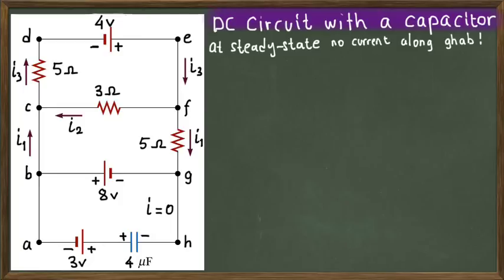Well, by setting this condition, we are ready to apply the Kirchhoff rules to our multi-loop circuit. So we start with, let's say, junction C, and of course when you put I equal to 0 for this branch, then there will be three different currents flowing in this multi-loop circuit, and let's assign these current directions and names like this. For example, on this branch between B and C, let's label the current as I1 and choose the direction like this.